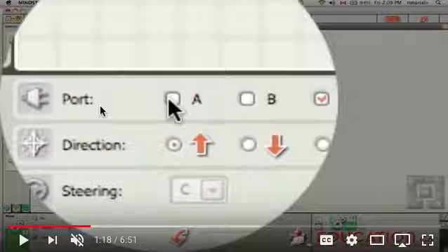These inputs then attach to the motors, which you have already seen because you've now built your robot. This robot has its motors attached to port A and port C, which allow him to control the motors where he has his wheels. So he's deselecting B because he doesn't have anything attached to port B, and reattaching it to A.